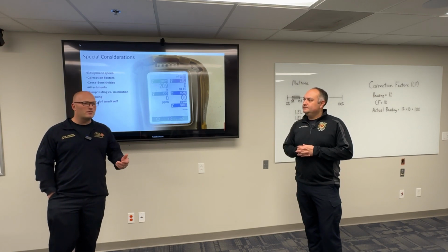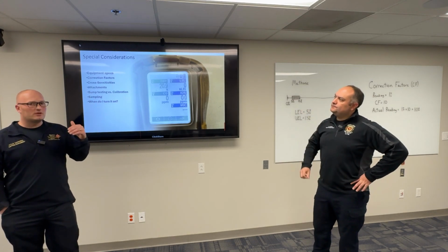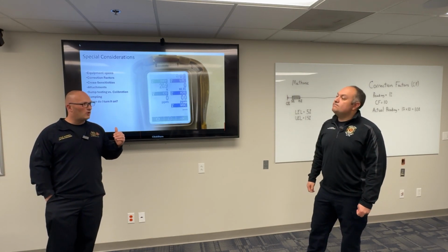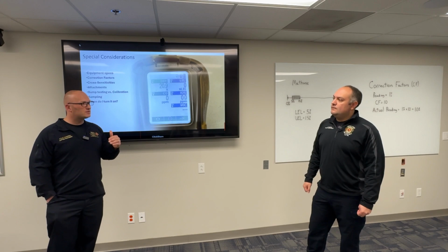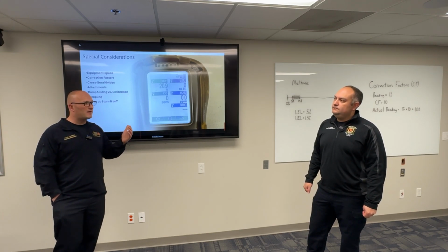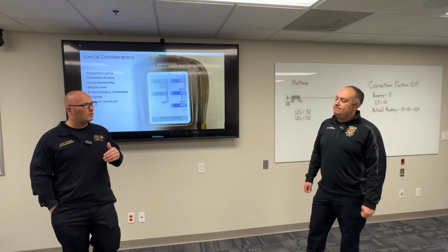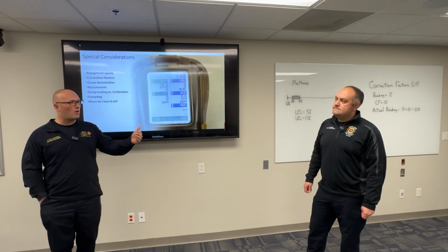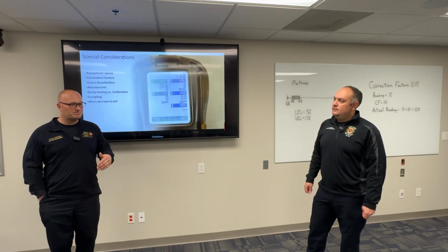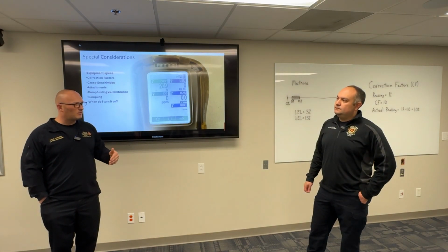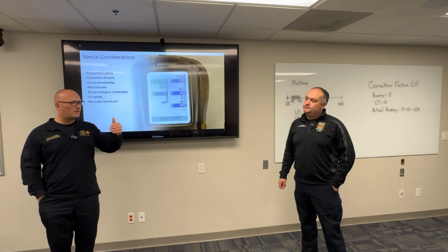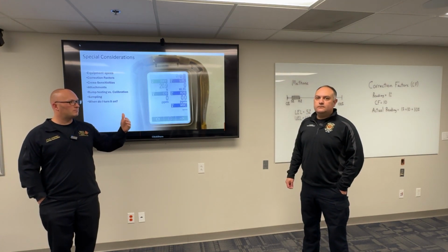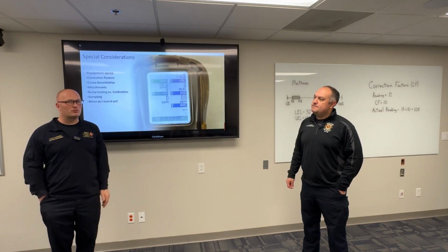So another good thing, to go back to the CO stuff, is understanding how the residential CO monitors are built and when they actually go off. There are certain readings, and the manufacturers are different, and that's worth looking into. At certain readings, they're built so that they don't alarm for several hours. That's set by OSHA and everything, I believe. So it might not go off for 8 hours, even though it's been at this much parts per million in the house. So that's something else to really understand.